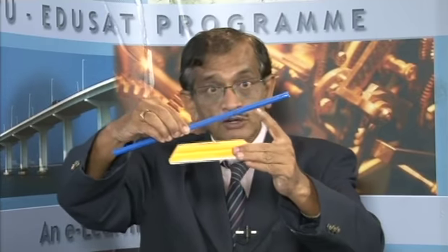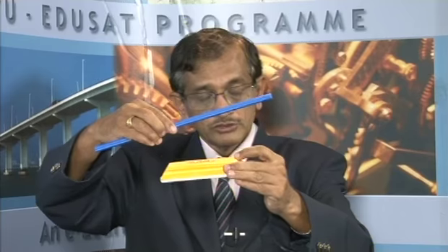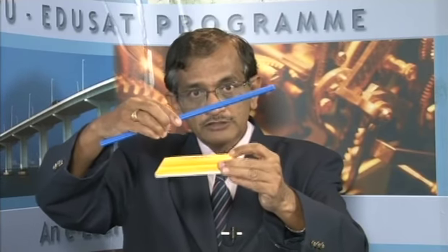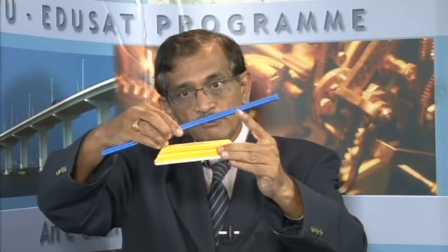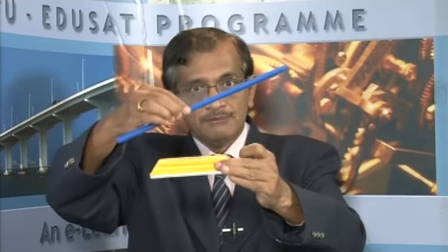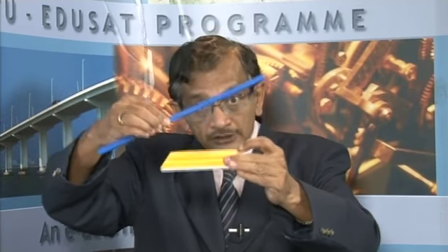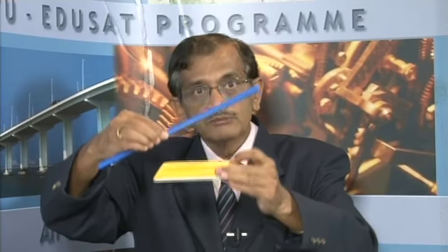Example, here it's 1 meter and here say it is 0.5 meter. Say time now, say 3:05. Again you see at 3:45, again the same 1 meter and 0.5 meter. Next day, 1 meter, 0.5 meter. It is a non-uniform steady flow. I repeat, it is going to be the same for all time, but it is different at different locations. That is called non-uniform steady flow.